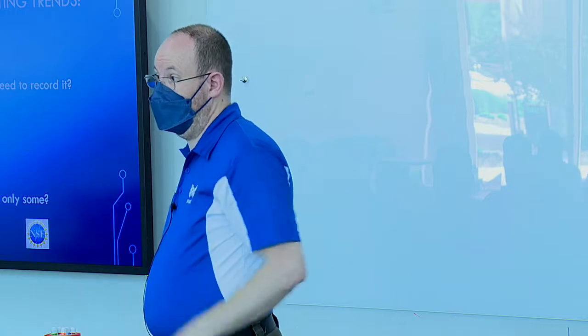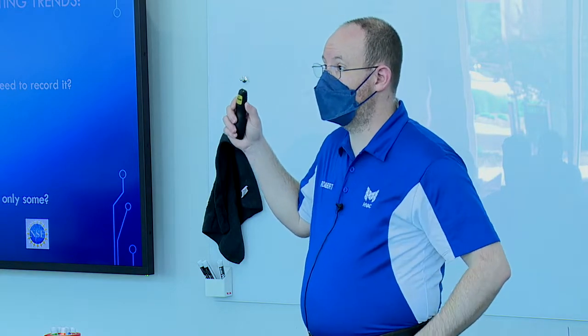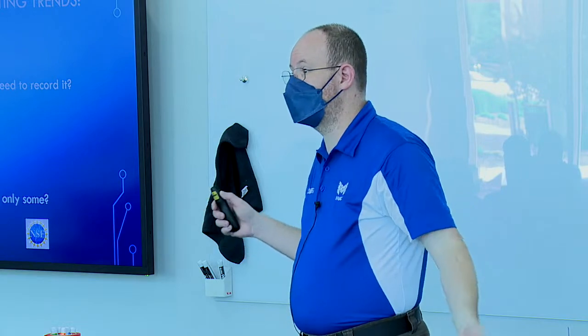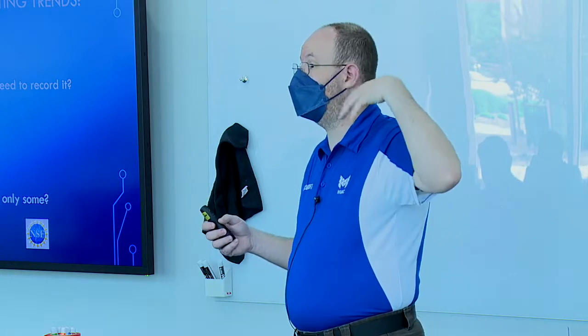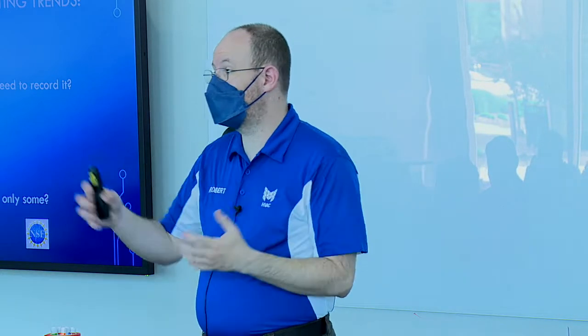So yeah, bandwidth should always be something we think about, and especially if we are using a local trend on a controller and pulling that entire trend from the controller for backup purposes, long-term storage, or if it's just a BACnet trend that we can pull over through BACnet. That is going to take up way more space, more bandwidth to get it over than just pulling the information from that sensor.